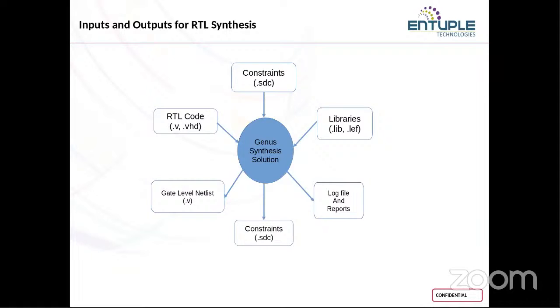So those are the three input files for your synthesis tool. And then you will perform your translation by using the syn_generic option, then the mapping process by using syn_map, and then your optimization process. After performing your synthesis, you will get your gate level netlist file as output, and then you will get your block level SDC file, which is in a tool understandable language.